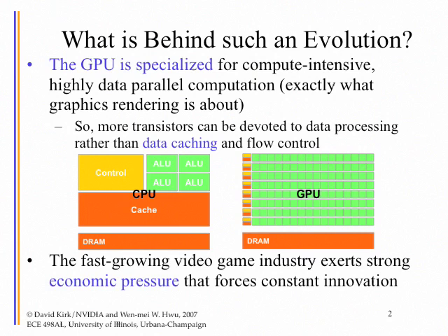Essentially, single cycle for first level caching, about 5 cycles for the second level caching, and about 12 cycles for the third level cache, compared to hundreds of cycles if you needed to go to DRAM. And the CPU pipeline is typically designed to tolerate cache hit latency. 1 cycle, 5 cycles, maybe 12 cycles.